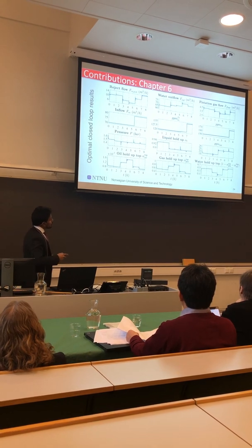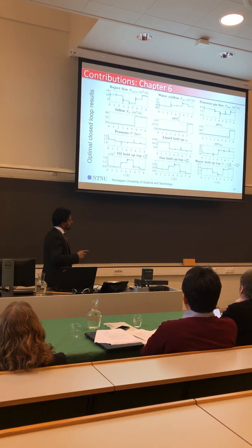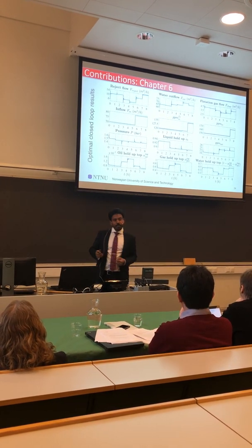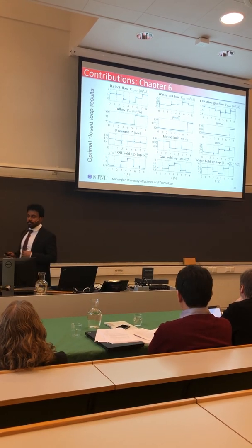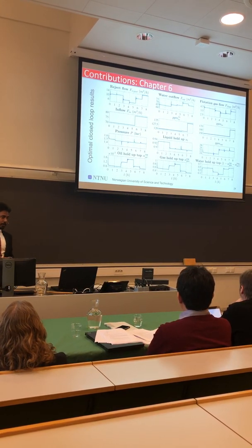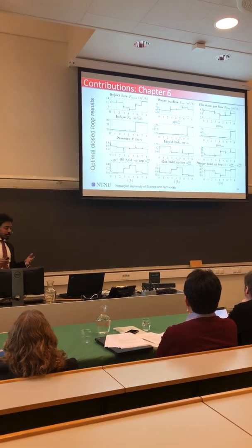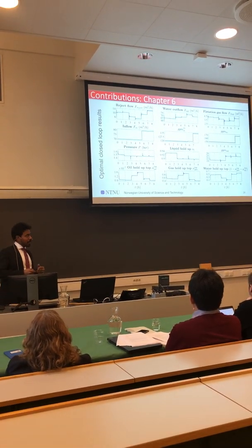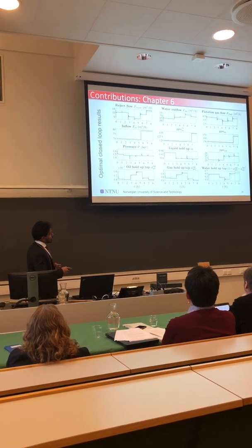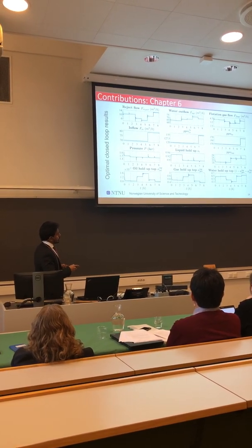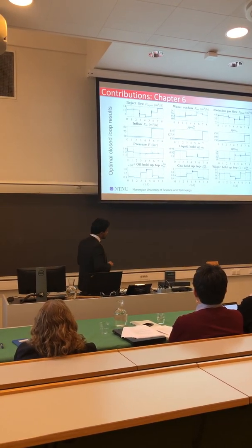You will notice that these values are not the same. I was talking about 30 ppm, but I keep it 25, and this is the reason. The reason why we do that is to keep a back off. The back off is to make sure that if we have not so good control, it will still have the possibility to maneuver between 25 and 30, yet keeping below 30.